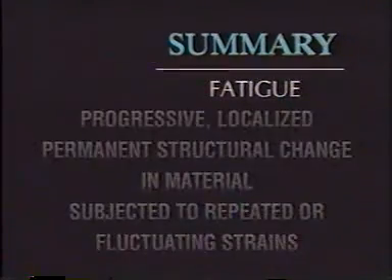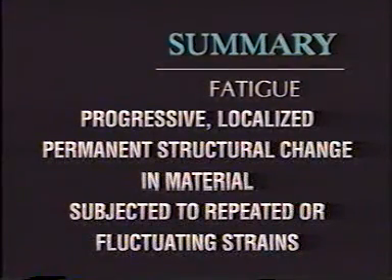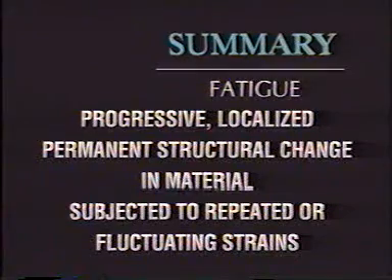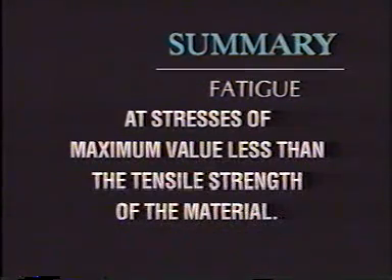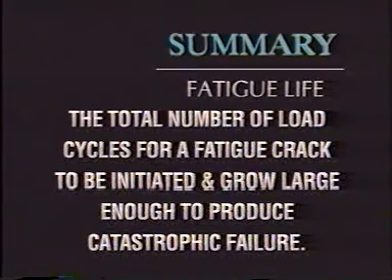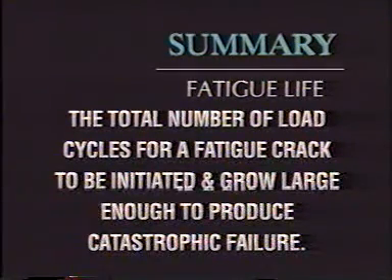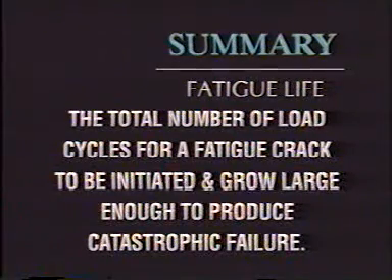Now, all this is fairly theoretical and complex, so before proceeding to the more down-to-earth study of fatigue, let's briefly review these factors that affect fatigue life and the methods used to predict it. Fatigue is defined as the progressive, localized, permanent structural change that occurs in a material subjected to repeated or fluctuating strains at stresses having maximum value less than the tensile strength of the material. Fatigue life can be defined as the total number of load cycles required for a fatigue crack to be initiated, then grow large enough to produce catastrophic failure.